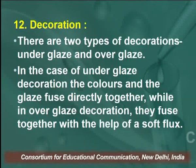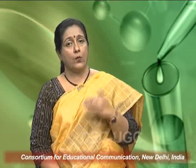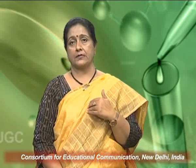Now comes decorations. There are two types of decorations, underglaze and overglaze. In the case of underglaze decorations, the colors and the glaze fuse directly together, while in overglaze decoration they fuse together with the help of soft flux.